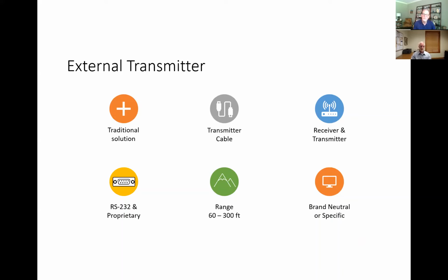If you're sending a user-defined identifier, like caliper 01, you can have 100 transmitters going to one receiver. If you're putting a channel identifier like 01, 02, 03 that goes with each measurement from a transmitter and gauge combination, then you're limited in our system to 30.